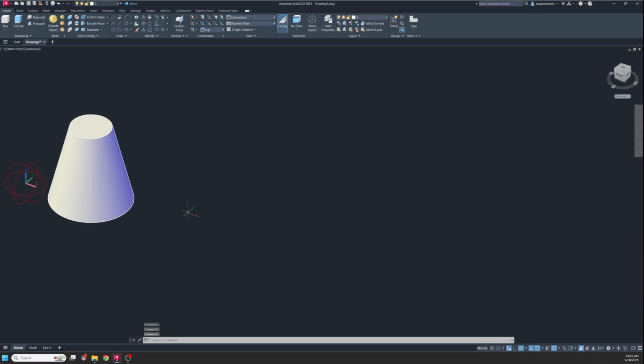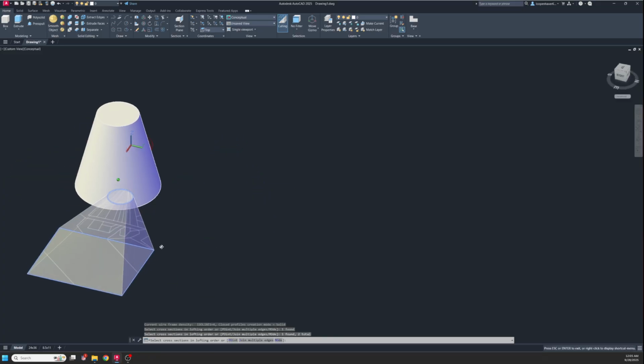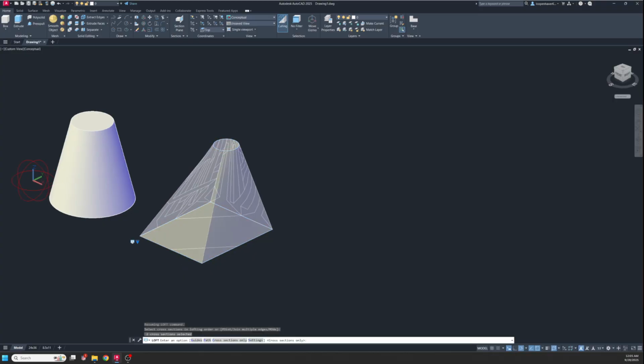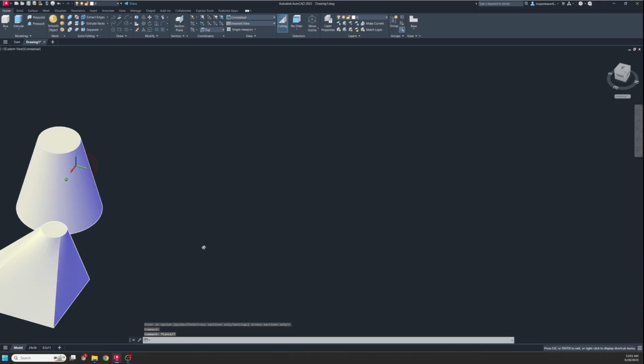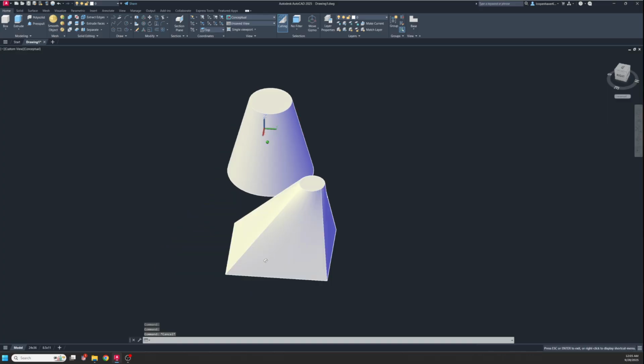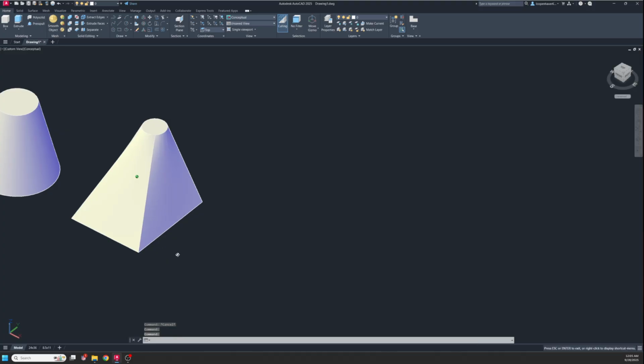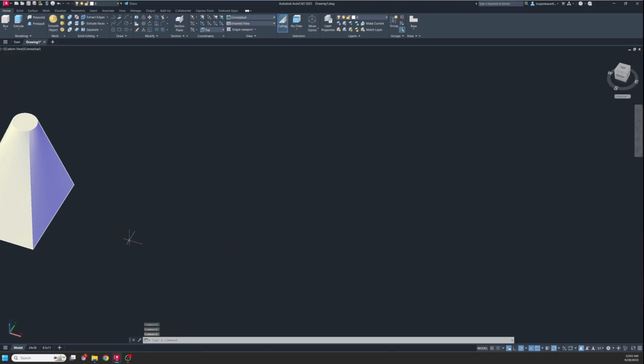And there are, of course, other options in there that you can play with, but that is essentially how Loft works. The shapes don't have to be the same shape. It can be a rectangle into a circle, and they also don't have to be perfectly aligned with each other. So if I have this one, where clearly that doesn't share an axis, and I move it like that, start my Loft command, click on the two shapes that are defining the new shape. And there we go. We see the preview. Enter, enter to accept. Lovely. So it's kind of a cool thing. Sometimes it's pretty much the only way to create the shape that you want.